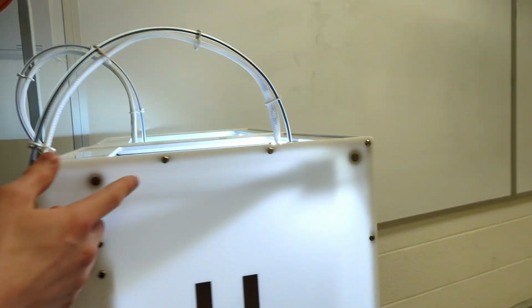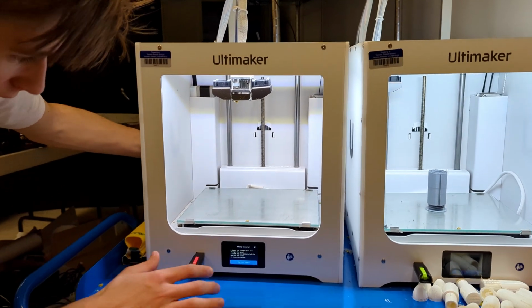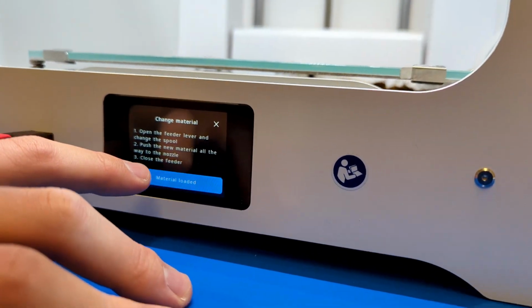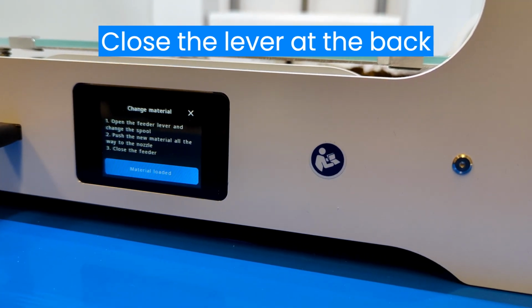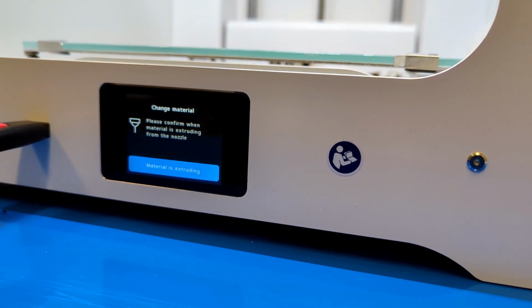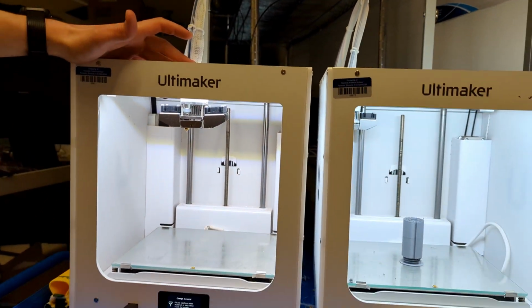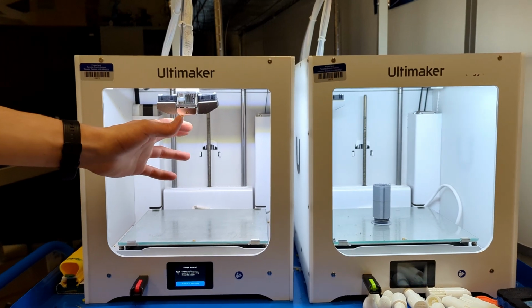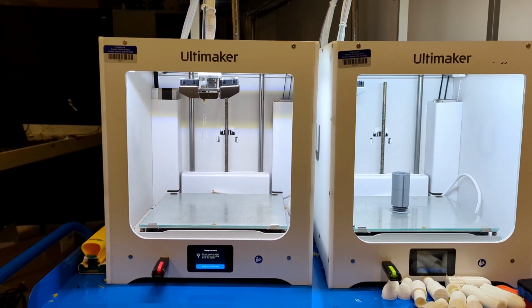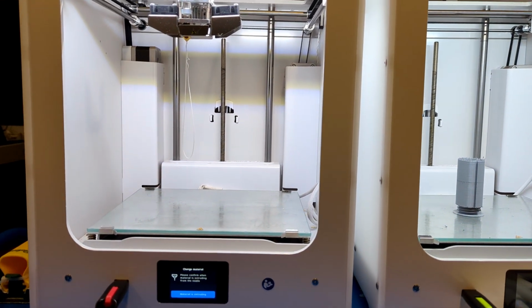So now we come back here, and we're gonna see it's in the end. So you're supposed to push it until it's very close to the nozzle. Now you close the feeder, and you say material loaded. Then it's just gonna slowly extrude that material, and when it does, see, we're starting to get white, so it means it's pushing, but there's still a bit of white left in the nozzle. Then we click material is extruding.